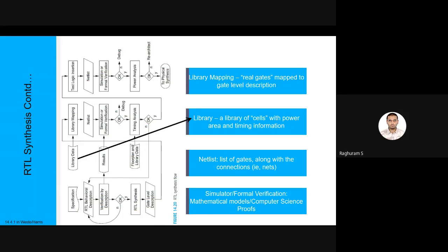Formal verification doesn't do that. It doesn't mean that we perform simulation 1,000 times and call it formal verification. It's a completely different way to do it, and it depends on a very important concept in computer science called Boolean satisfiability, meaning does this particular system of gates satisfy some condition, and it's possible only in digital because we have only two values.